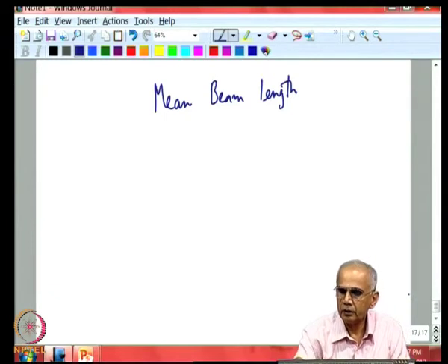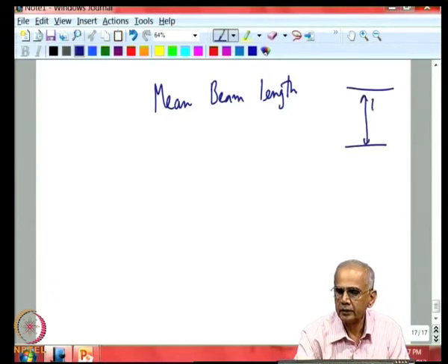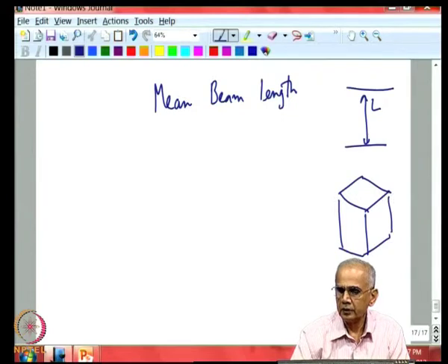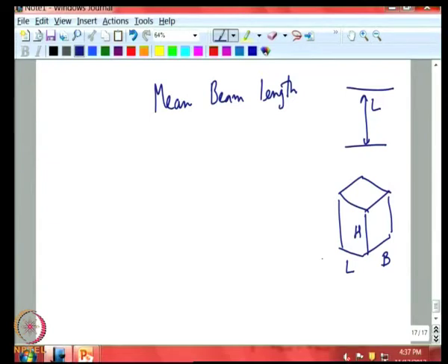If it is simple parallel plates, the dimension of course is this length, but when you go to 3 dimensions, there is length and there is breadth and there is height, and we should know how we should combine these 3 length scales to get the effective length scale to be used for calculation of emissivity. We will write emissivity 1 minus e to the power of minus A into LE. We must know what that LE is.